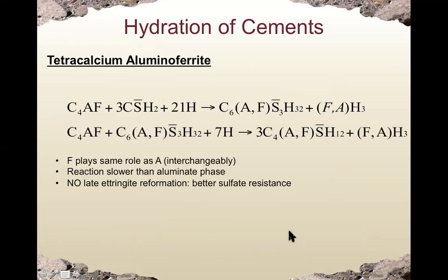And this is hydration of C4AF, very similar to C3A, but the reaction is slower compared with C3A, and it will not cause late ettringite formation, or in other words, sulfate attack.